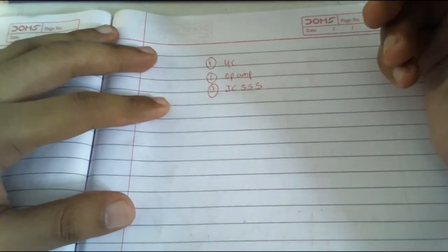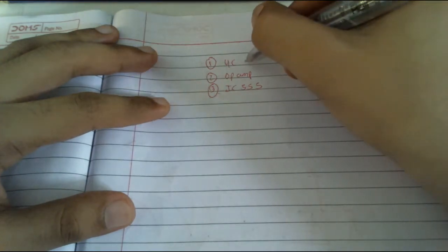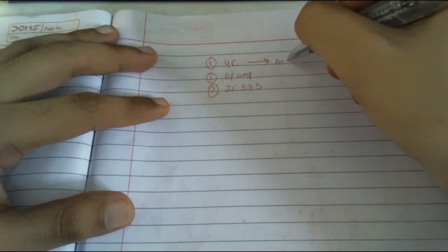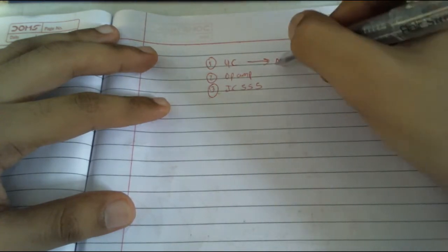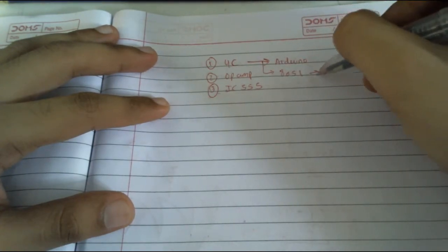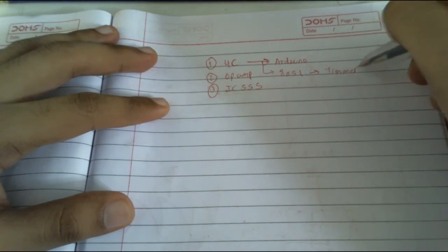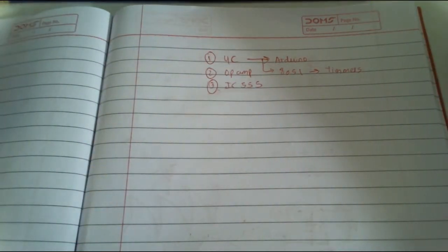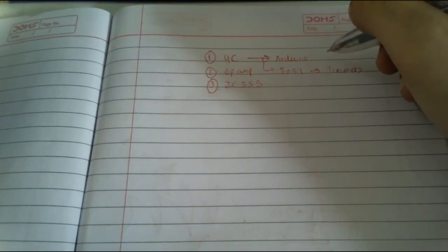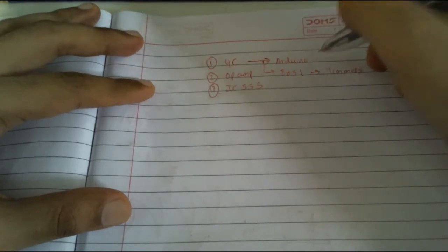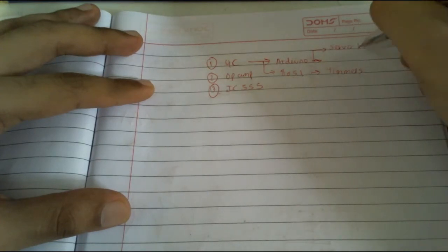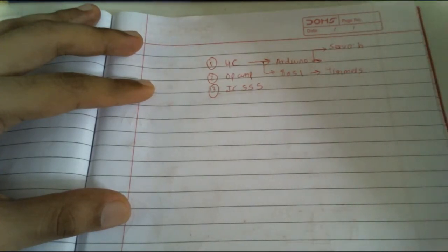So if you have many output devices that require a PWM signal, you can go with this microcontroller option, and you can use an Arduino or any 8051 based microcontroller. If you are using 8051, you need a good knowledge of timers to generate a perfect delay of 1 millisecond and 19 millisecond, on time of 1 millisecond and off time of 19 millisecond, to vary the duty cycle. If you are using Arduino, they have one library called servo.h.